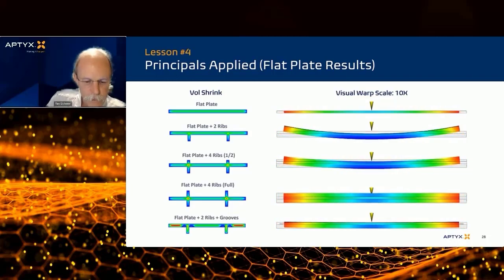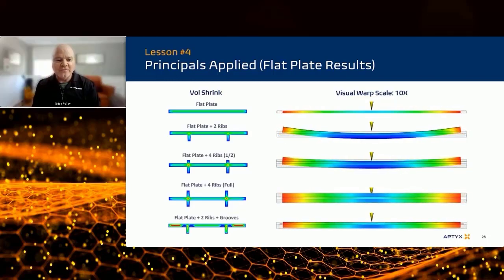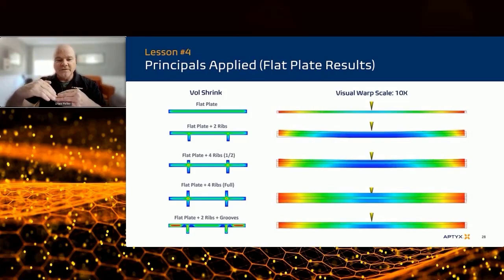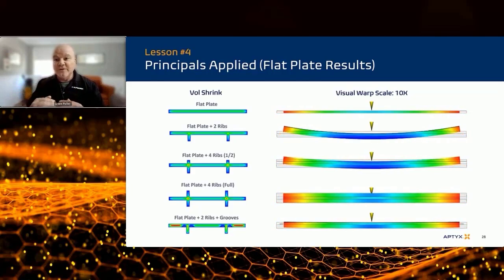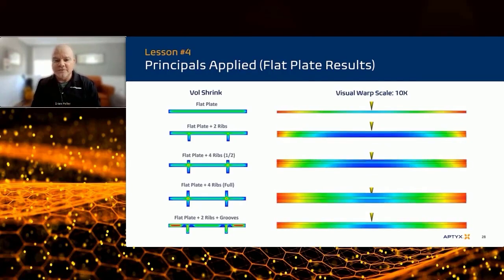Yeah, it's like a 2-for-1, and you need to play King Solomon. For warpage, it's a great way to add on the non-cosmetic side a feature that will encourage balanced loads. And the other side is we see people put moats around features like bosses and ribs to reduce thickness for cosmetic reasons, to reduce the shrinkage in there so they don't get a dip or sink on the top surface, the cosmetic surface. But if you go too far, you can actually create a visual in that thin area where it looks like a bump or a splay almost, or discoloration. So you got to be careful about how aggressive you get.